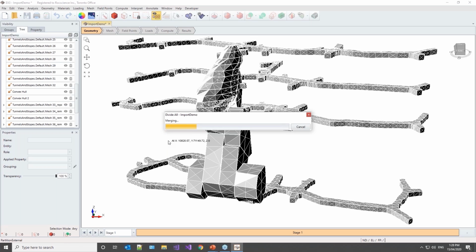So if those 2 volumes were assigned different materials, then what should that overlap be assigned to? Well, now that is a separate piece, so you can assign that overlap separately from the 2 separate pieces. So this has to be done for every model just so that you end up with those distinct volumes that we can interpret correctly.